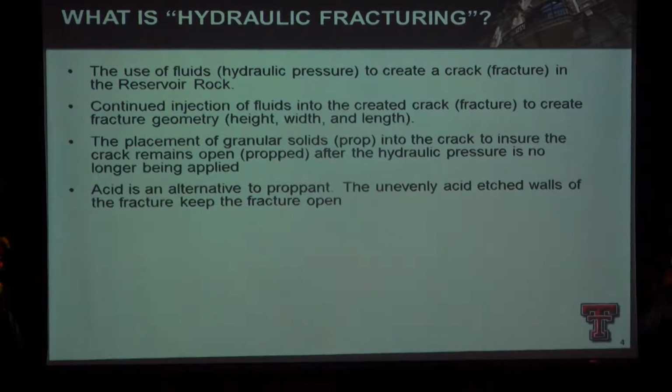We oftentimes, in some reservoirs in West Texas, which is where I'm from, pump acid that you use in your pool. Muriatic acid, hydrochloric acid, same acid you use in the pool to keep it clear and clean. We use that. It reacts with the limestone, if you have a limestone reservoir, to actually react with the rock and make paths for the fluid to flow.